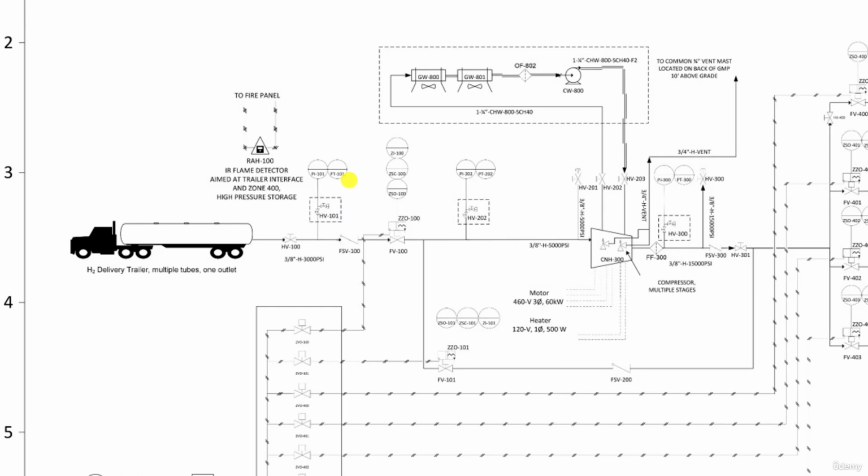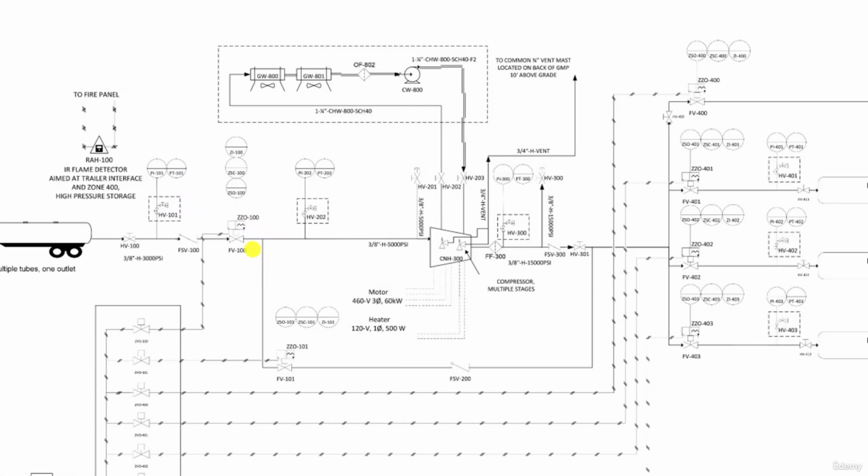Now, moving on further to the right, we have an air-actuated valve. Recall from the legend and specifications P&ID we saw in the previous video, we know this is a spring return close, meaning the valve is kept open by the action of air and is closed by the action of the spring as soon as the air source is shut down. On this P&ID, the air inlet to the actuator is on this side, and the spring is depicted here. We'll come back to this arrangement later on.